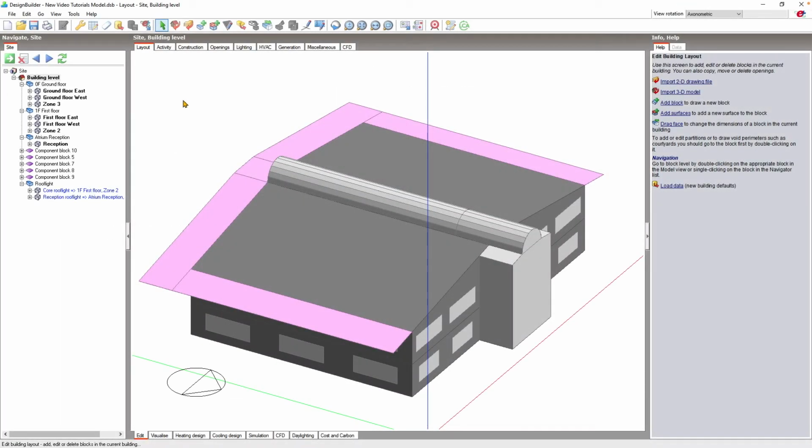Before setting your calculation options, you can switch off any zones that are not required. For example, you may only want to look at the preliminary results of a few of the key occupied zones during early stage or QA checking simulations. Switching off less important zones, such as the WCs and storerooms, can help to speed up these test simulations.